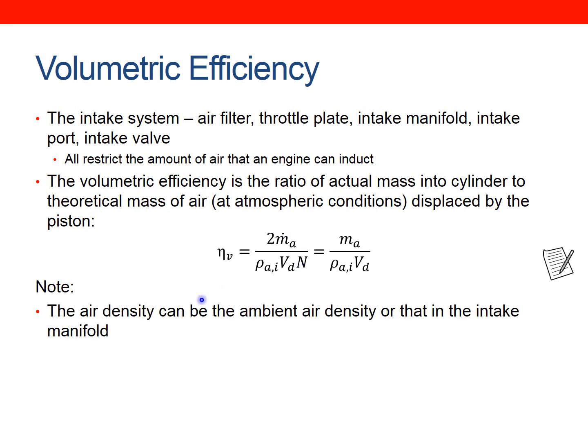So the air density is important. It depends which one you use, because the air is a compressible fluid. Its density will change with both temperature and pressure, so its density is going to change all the way through the intake system. So it's important to clarify which density you're talking about.